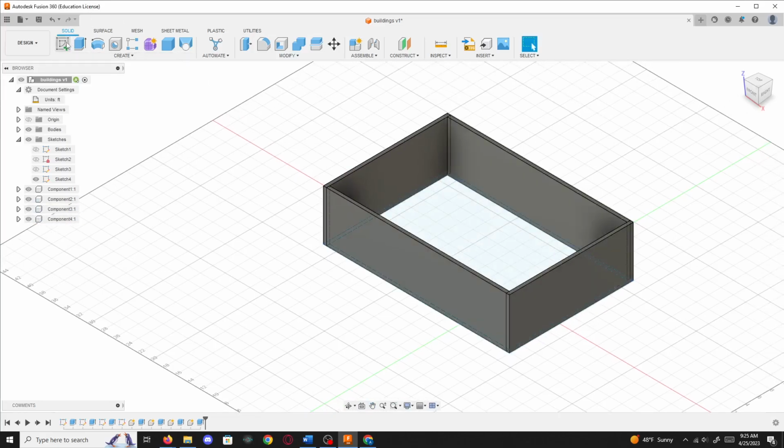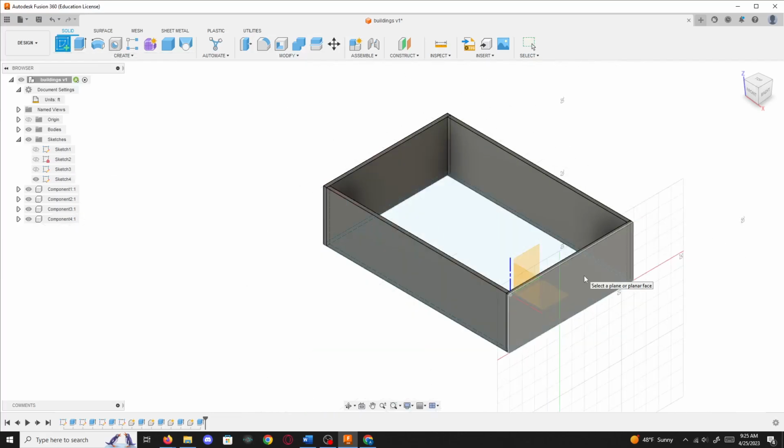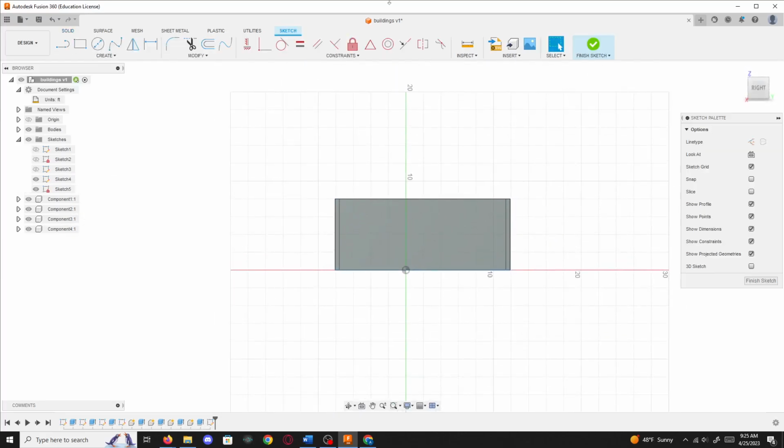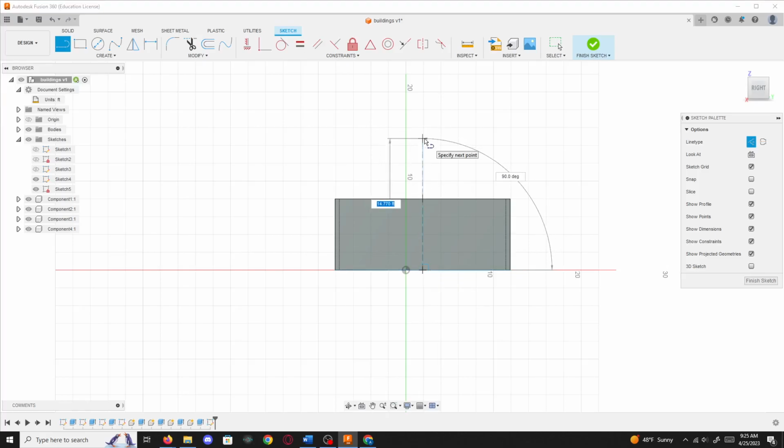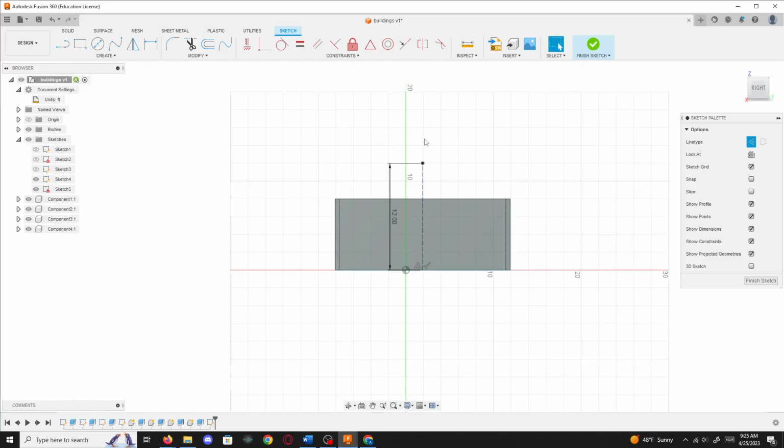And now we're going to do the roof similar. So I will click the side, create a sketch on one of the walls of my shop, turn on my construction line, select my line, snap to the center, see how the triangle appears. Gonna go up 12 feet, hit enter to place it, turn off my construction line. Now this time, we're gonna do it a little different.